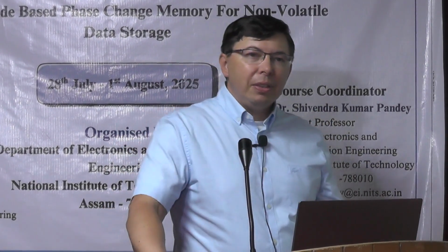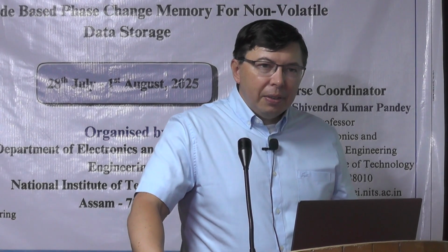Oh, please. So, Professor, in slide 10, you were discussing that in vacancy ordered structure degree. Yes. So, is this the rule of thumb if you want to create a vacancy ordered GST? Like we need to keep it 160 to 220 degrees. So that is when we get the vacancy ordered GST. Yeah, it's a little bit composition sensitive.